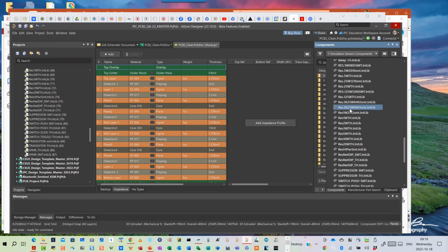And even then, if you've already created an integrated library for just devices, just start extracting parts out of it. Make a new library. You can re-extract the sources out of the integrated library. Yes, so just re-extract your source, schematic lib, PCB lib, and start creating a bunch of schematic libs for digital ICs, analog ICs, resistors, capacitors, and so on. Just, here's all my caps. Throw them into that one and remove them from the first one, and so on.